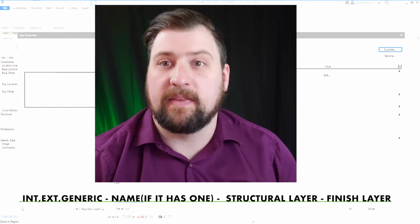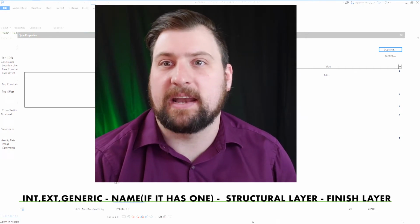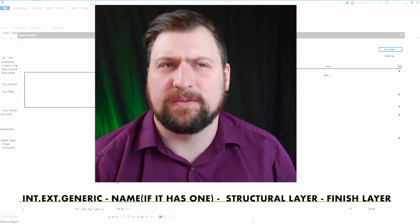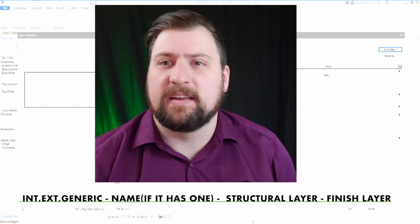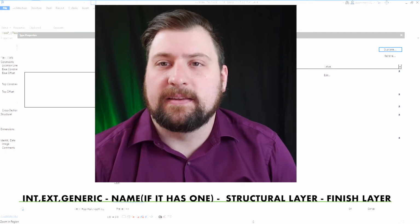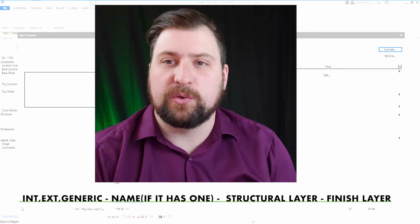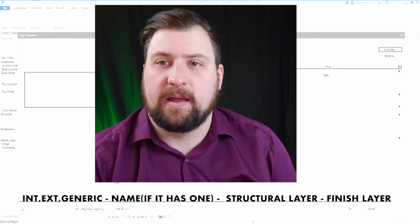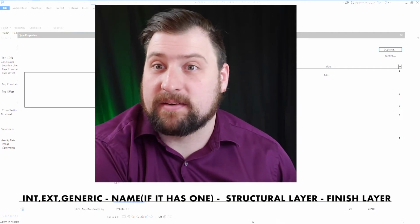And then the finish layer, a description of what the finish layer would be: brick, siding, stucco, that sort of descriptor. And then you can add other information as well, like thickness or something of that sort, so that it makes it easier for other users to select the right wall type, or even for yourself if you're coming back to the project at a later date.